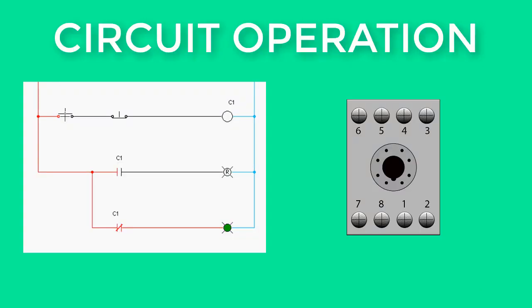One of the benefits of understanding ladder logic is to make field wiring easier. Relays typically have all of the connection points identified with numbers. Transposing the relay base numbers to the ladder logic diagram can make field wiring much easier. In this example, the corresponding coil and contact numbers are added to the ladder diagram.